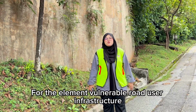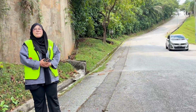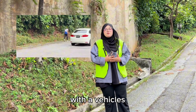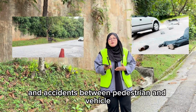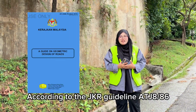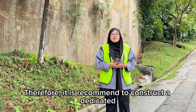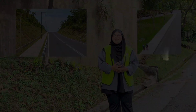For the vulnerable road user infrastructure element, we observe that no sidewalk is provided along the road section. Many students use this road for walking and jogging in this area, so they have to share the roadway with vehicles. This situation increases the risk of conflict and accidents between pedestrians and vehicles, especially during peak hours. According to the JKR guideline APJ 8-83/2015, sidewalks should be provided in areas with high pedestrian activity. Therefore, it is recommended to construct a dedicated sidewalk to improve pedestrian safety and accessibility.